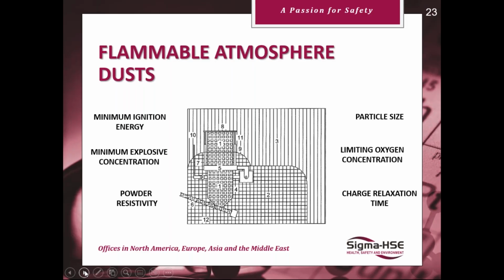Do you know the powder volume resistivity of it? Is it insulating, conducting? And how long does the charge remain on it? Is it 28 days like the active pharmaceutical ingredient, or is it less than a second? And the minimum ignition energy, is it down below 3 or 1 millijoule, or is it up to a joule?